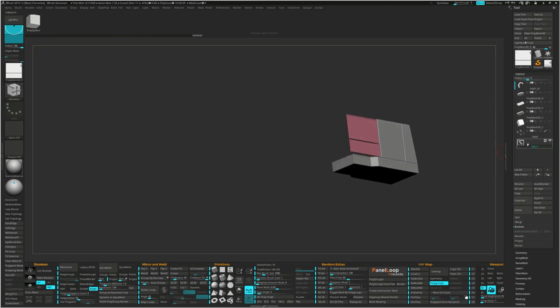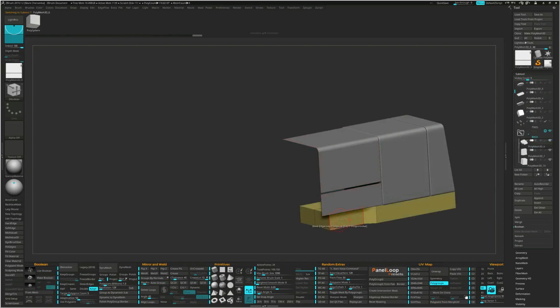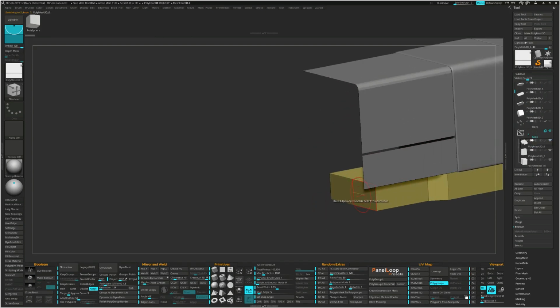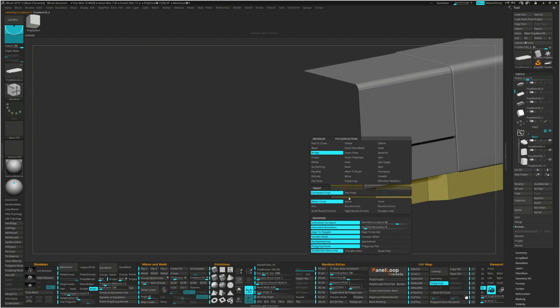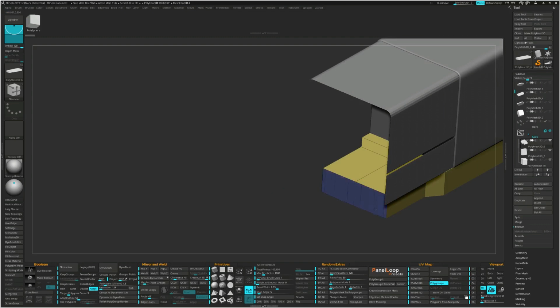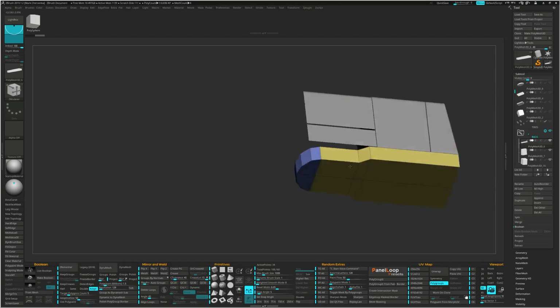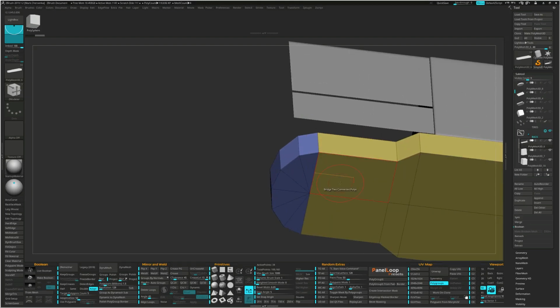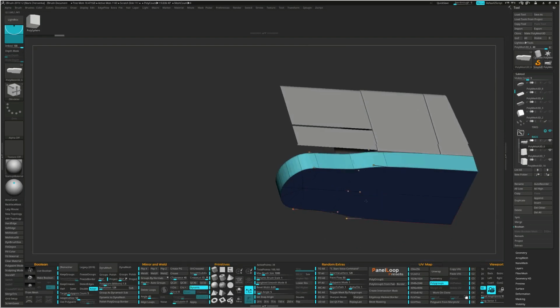Now we can turn off all the eyeballs for the subtools and work within the folder. Click on the bottom subtool and hover over a polygon. We want to bridge connected polys as a circle with modifiers of polygroup flat and triangle sides. Group by normals and crease PG. Turn on dynamic and add an edge loop to tighten up the form.